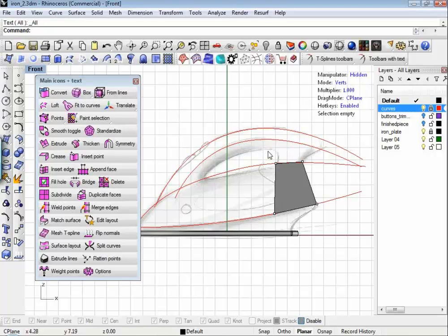The hotkeys for the selection tools are the A tool to get verts, and if you watch up here this will change. The S tool for edges, D for faces, and F for objects. There's the manipulator up here. You can also get this by clicking through, if you click up here in the heads-up display. And then the other one is the manipulators, and the Q tool hides them. The T translates, if I pick an edge here to start with so you can see it.